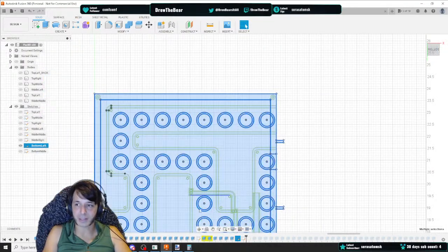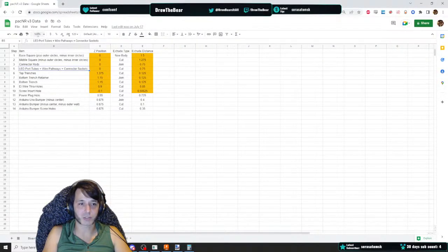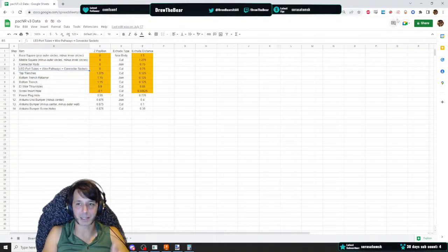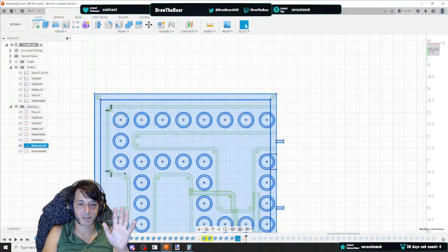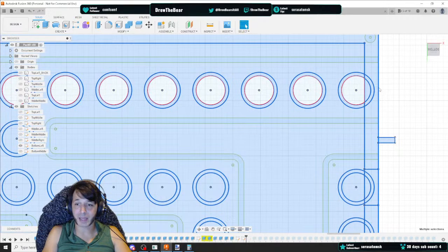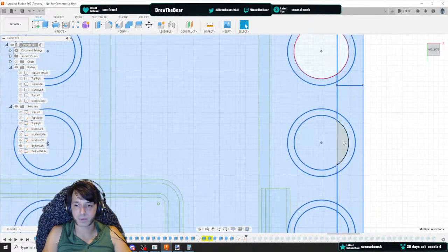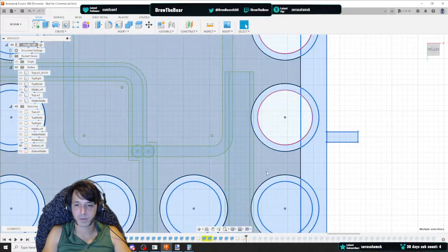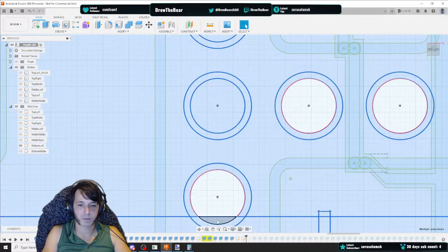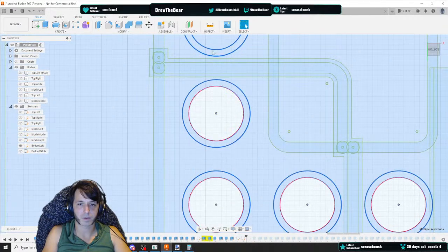And I'm going to deselect the things I don't need. So if you look at the extrusion, I have even written down everything. So like the base square plus outer circles minus inner circles. That's referring to these tubes. So I don't need the inner circles. I deselect these because these are going to be empty space. There's nothing that gets printed there. Almost done.